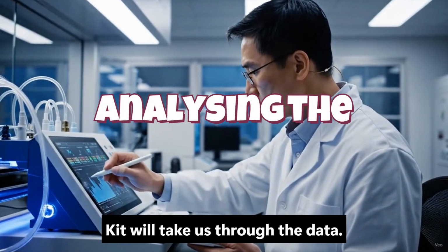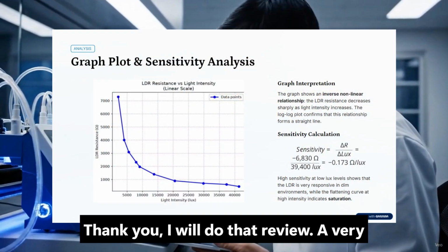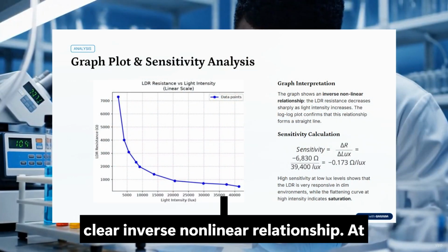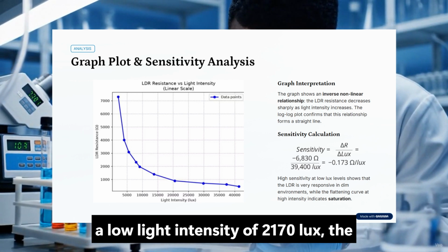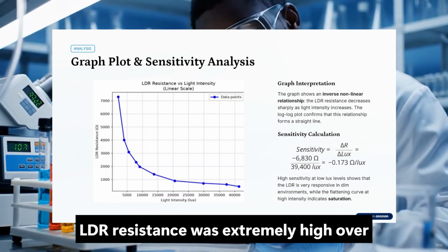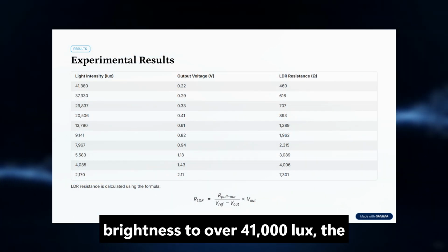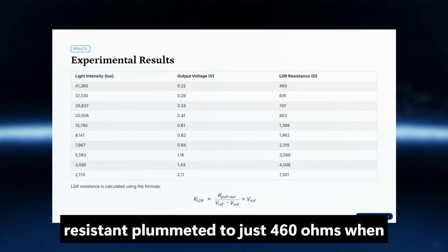Now, Shaukit will take us through the data. Thank you. Our data reveal a very clear inverse non-linear relationship. At a low light intensity of 2170 lux, the LDR resistance was extremely high, over 7300 ohms. But as we increase the brightness to over 41,000 lux, the resistance plummets to just 460 ohms.